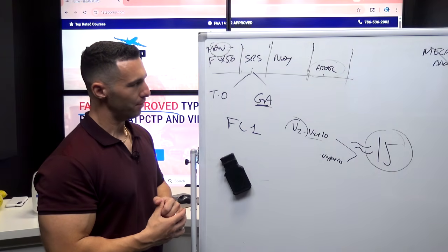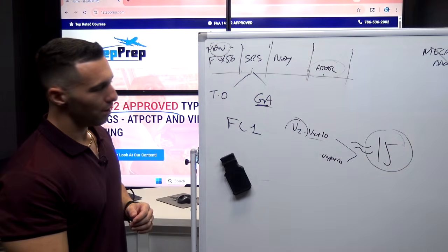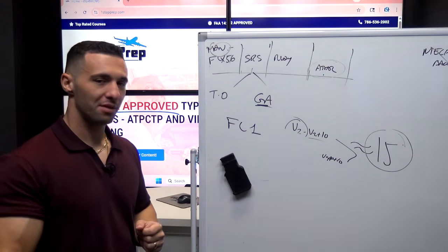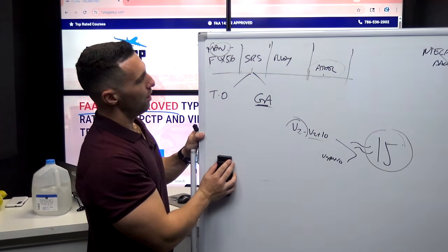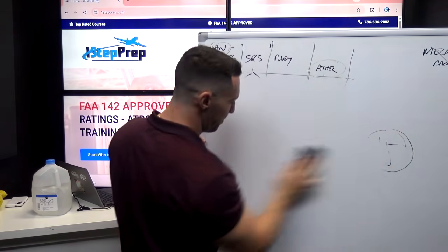Runway, of course, tells us that we have a localizer to track, and then finally auto thrust in blue. As I said earlier, if it is indeed blue, it's armed, white meaning active. Okay, that was a random whatever that was, but hopefully that made some good sense.